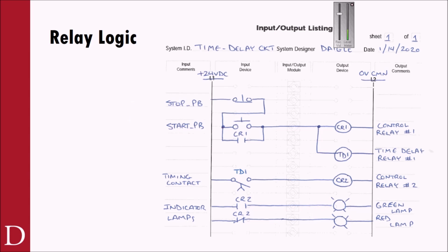As you look at this, what do we got here? So, I might even just ask you to analyze this and give me a little paragraph as to what this circuit does. You'll notice the normally closed stop, which I might actually ask you as well, what color wire. So like this would be a blue wire. This would be a blue wire. You might say, well, where do I change to white with blue stripe? Well, this is essentially my load. So this is where I would go white with a blue stripe then.